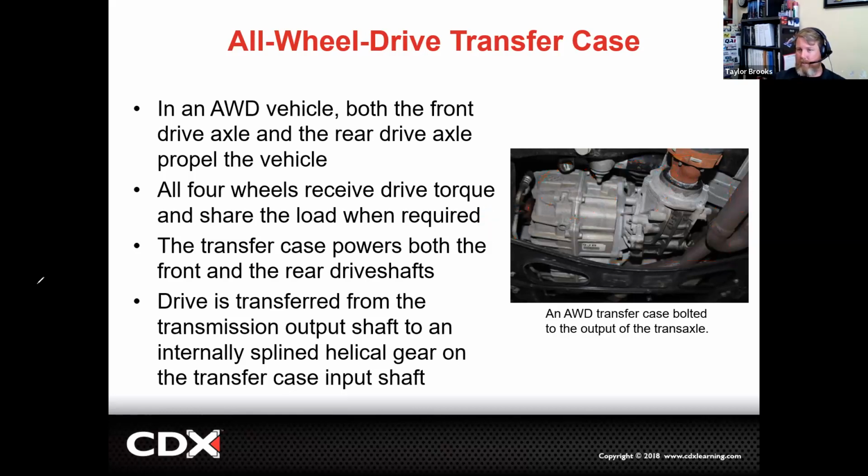We can have everything as low as 15 to 85 split, up to a 50-50, dependent on the chassis application. There are some weird applications. There is a Ferrari FF out there that, instead of a transfer case or a PTO, has two transmissions. There is a conventional transmission on the back of the engine that will send the majority of the power out back, and it gets about 85-90% of the engine's torque.